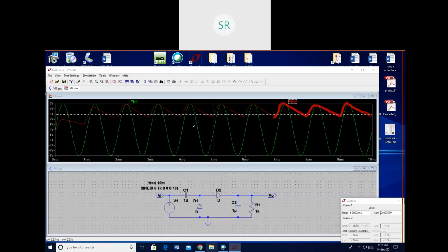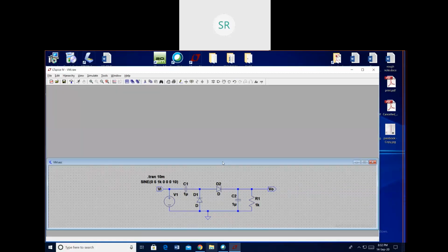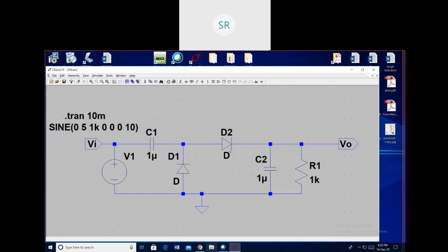So that you can easily do. Within a minute you can check all this information. Now let us see, I want to change the diode parameter. So I want to make this diode an ideal diode with V gamma 0. So let me keep this R value 100K itself.